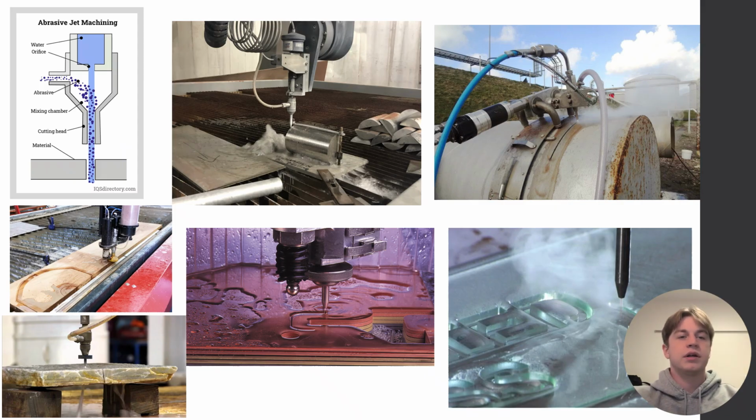These are a few examples of abrasive jet cutting and their applications in the field. The top left is just the overall process for abrasive water jet cutting. It shows the abrasive material coming in and mixing with the water to cut materials. The top middle is cutting a very thick shape that abrasive jet cutting can do very easily. In the bottom left, you have brittle materials, and on the right is also a brittle material, glass or hard plastic, which saw cutting has a hard time cutting.